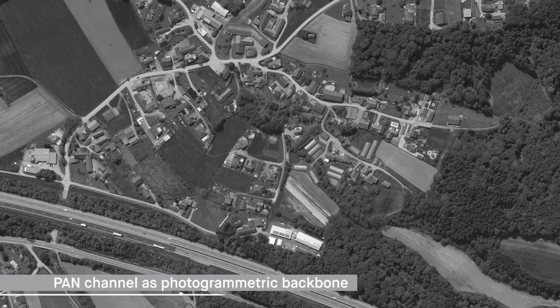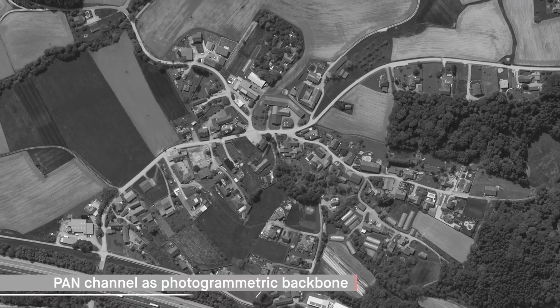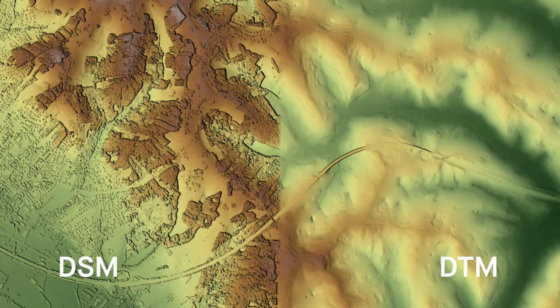But in the Condor, it is not only about the color imagery. Besides the color imagery, that camera system also collects pan imagery, and that pan channel acts as a kind of photogrammetric backbone. So it is possible, together with the UltraMap workflow, to generate 3D point clouds, DSMs, DTMs, which are then later used to auto-rectify the imagery. So at the end, this sensor gives you all the data you need to generate ortho imagery. There is no additional LiDAR data set or LiDAR flight required.